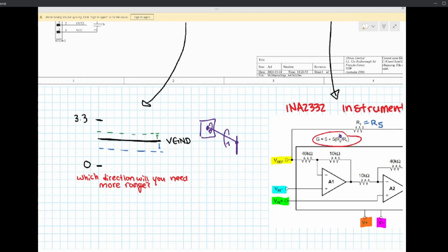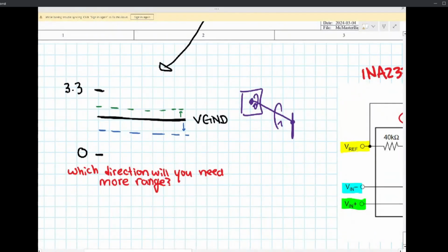I think it's on the deceleration side, on the braking side, because it is more instantaneous, and the engine can only supply so much input torque, especially because it's going through the gearbox and through the CVT, so it's not really instantaneous. But that would be an argument for biasing your virtual ground toward the direction of the range where you want to see something more granular.